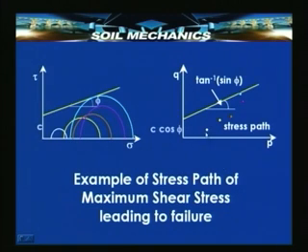Now, if one knows this stress path, one knows what kind of stress history the soil has gone through and what has led to failure, and that is very important because that throws insight into the behavior of a soil subjected to loading and how it gradually tends to move towards a state of failure.